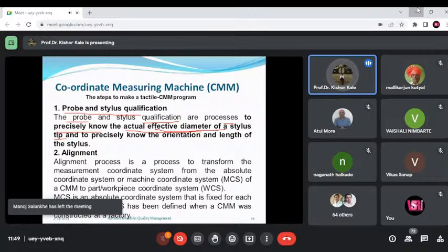Okay, so the corresponding points are decided by choosing the closest point, minimizing the distances, and the corresponding points should coincide. Once this is done, the closest point is suitable for the matching of surfaces, but not for the tolerance verification process when the tolerances are prescribed. This is the closest point approach we can use when there is no datum.